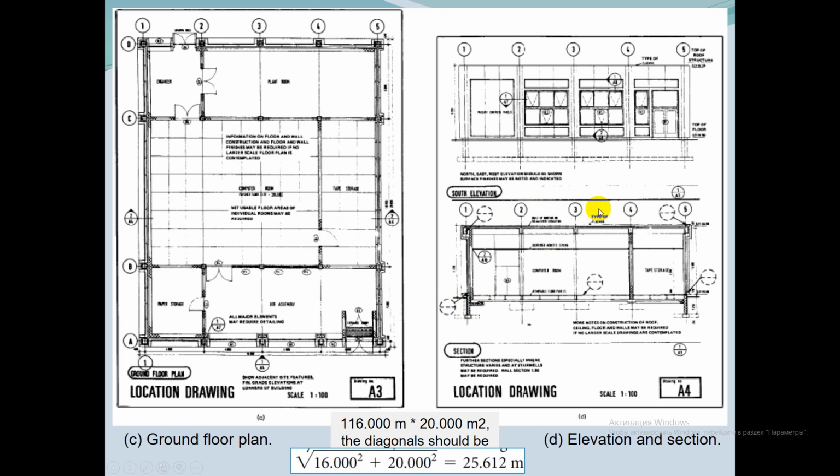The survey sets up the property lines as shown on the site plan. The building corners are then set out by measuring the setbacks from the property lines.